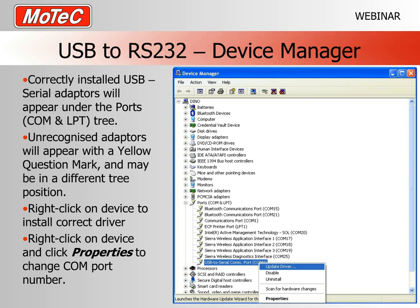Typically there'll be an entry called unknown devices, and in that case it will often have a yellow question mark next to it, and that is an indication to you that the driver has not been properly installed and you need to take measures to do that. It will never communicate with MoTeC devices while it's showing that yellow question mark in a little circle.